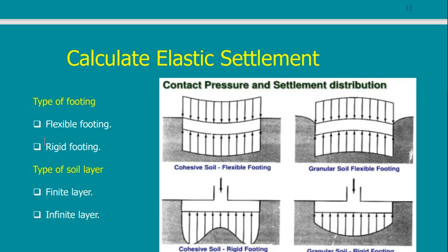If you are standing on soft soil and I give you maybe a piece of plastic to stand on top of it, this piece of plastic will bend below you and it will be affected by the soil and it will affect the soil, but your load will be concentrated at the middle of this plastic raft where you are standing, and at the edges you may not have the same effect.